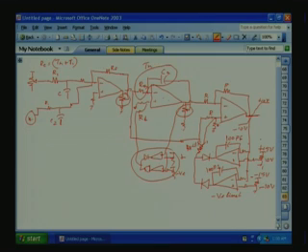Okay. So, we will ensure that whenever a large error happens, this capacitor will never go to more than plus 10 or minus 10, and the operational amplifier will never saturate. If it saturates, what happens? It will take a longer time to come out of this. While running, we can use it for fine tuning.